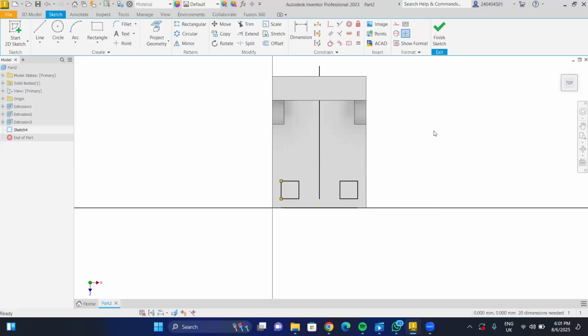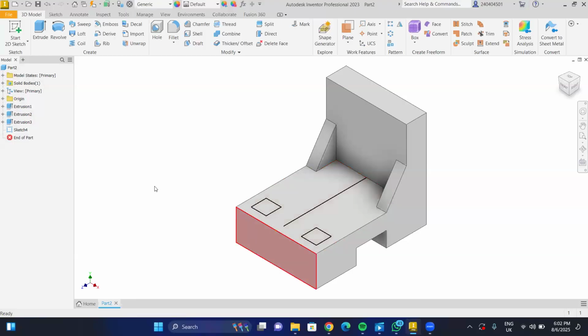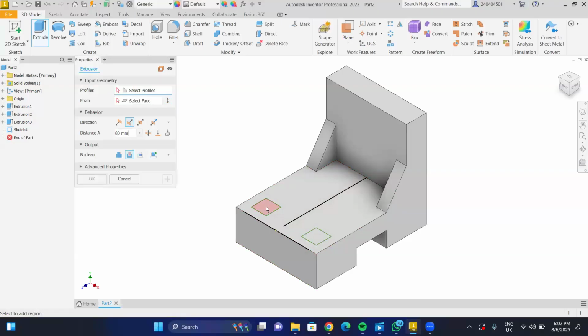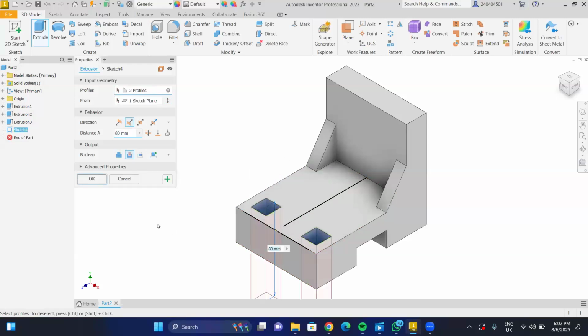So we can now finish sketch. Click on finish sketch. Okay, so you have this. So come to extrude again. Extrude. These two automatically pop up. I want to cut, so I will just click on cut. Next, through all. I'll use through all. Through all cuts the hole out to give you that there's a hole inside. Next, it asks you for a distance, a depth that you want to cut to. So best to use through all. All right, so click on OK.